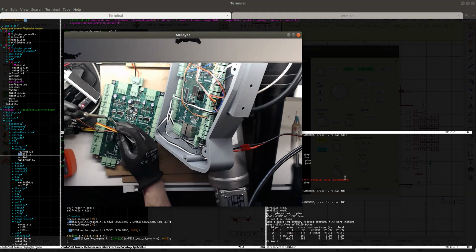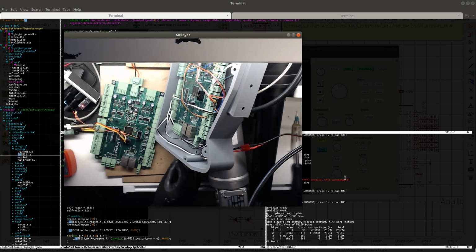I'm going to remove the solder mask, just like I did on the other chip. Removing the solder mask from the ground pad, which according to the datasheet does not need to be connected to ground. But apparently there is some purpose in connecting it to ground. Or maybe it's just the pins that are not connected. Oops. So